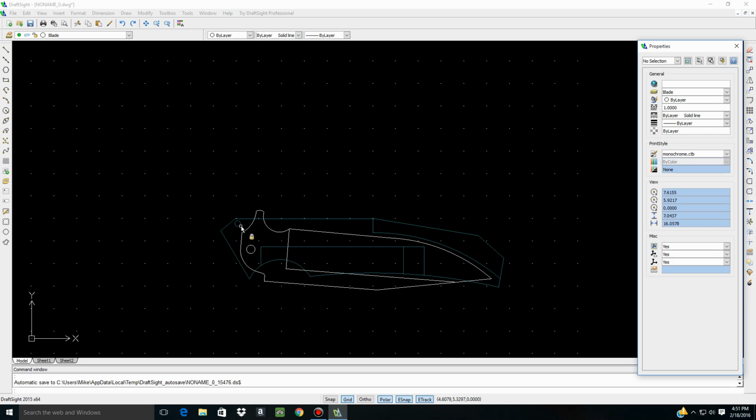We could bring out the flipper tab. If we do touch the lock face, it's going to have to come out more. And we're going to get awfully close to this pin. So we might have to do a combination of everything. But remember, once you change something, you have to change everything. You can't just pull this out and expect your lock to lock up and everything to function. Now remember, we want it all hidden inside the handle, so keep that in mind as well.